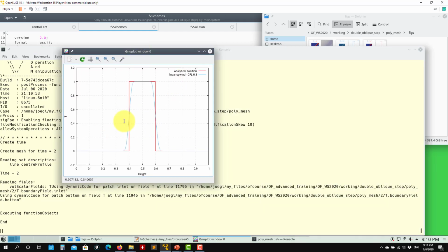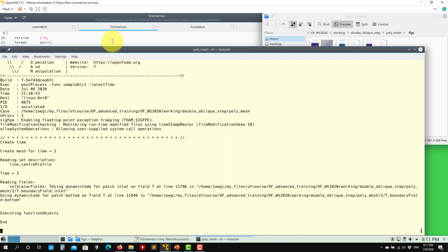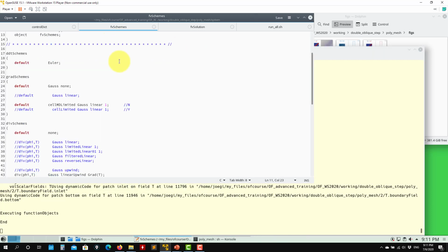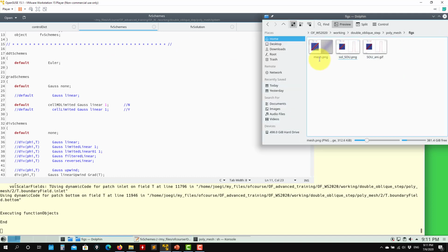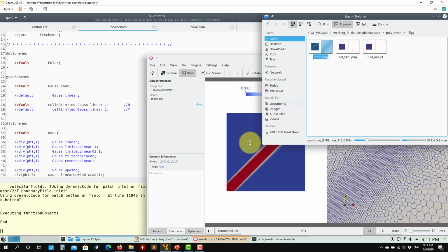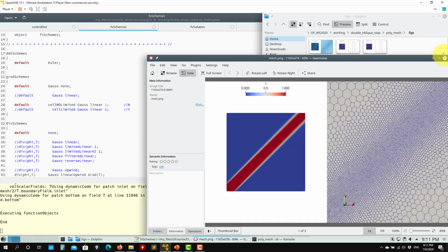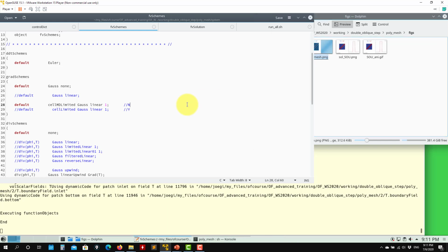Okay, so I'll see that we increase the time step, no problem in the solution, it's still very bounded. Okay, so see also the influence that some meshes might have better approximations to fluxes and better computational gradients. In this case, the polyhedron mesh computes better those gradients. And actually the polyhedron mesh was derived from the triangular mesh, okay? So you get the triangular mesh, and using those triangles you reconstruct this polyhedron. So it was exactly the same mesh.